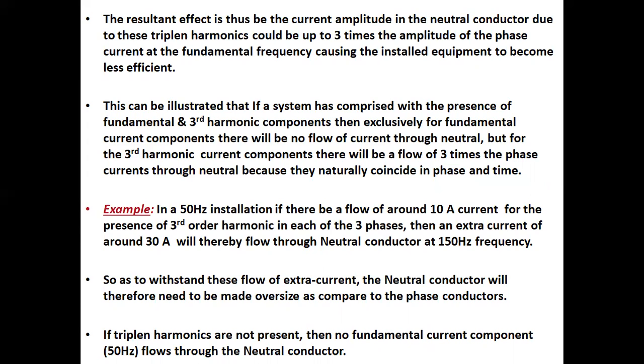So as to withstand this flow of extra current, the neutral conductor will therefore need to be oversized as compared to the phase conductors. If triplen harmonics are not present, then no fundamental current component flows through the neutral conductor.